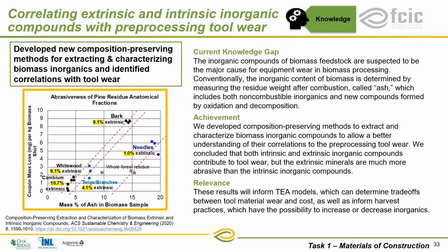In this work, the researchers on this task showed dramatic differences in wear rates among different anatomical fractions of hardwoods and pine. And they demonstrated that it's largely caused by the presence of extrinsic organics, the organic material, and extrinsic inorganics, the inorganics that get brought into the biomass stream during the harvest, during the transport, during the storage.